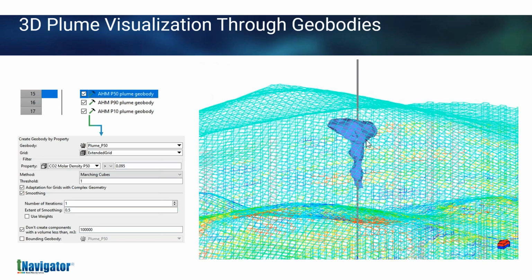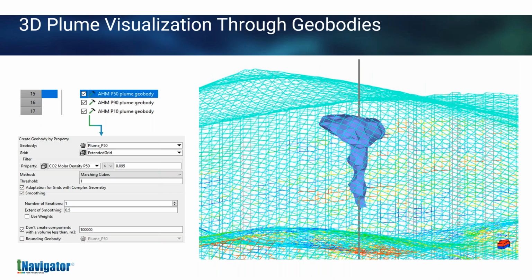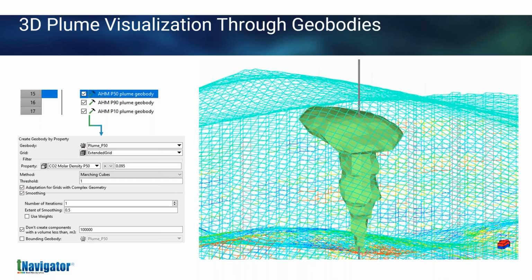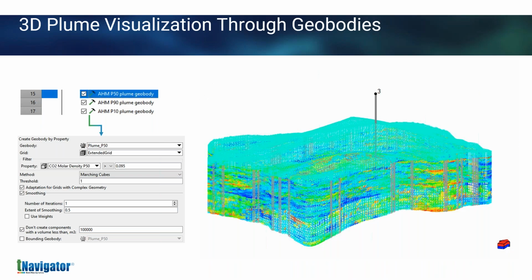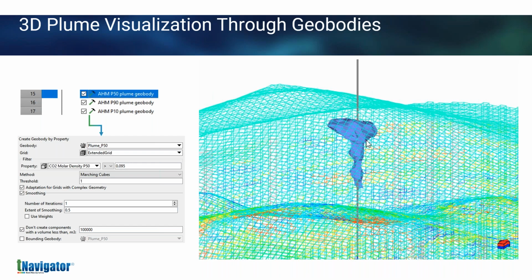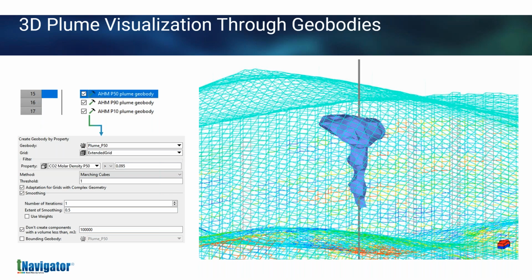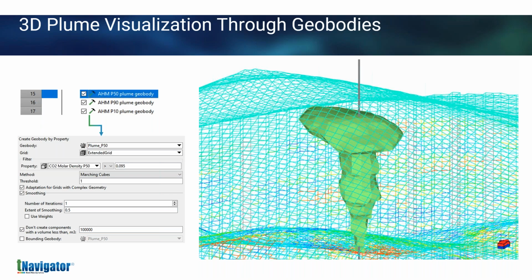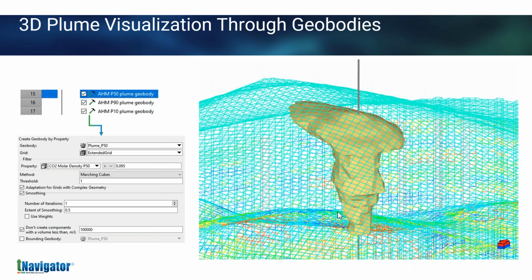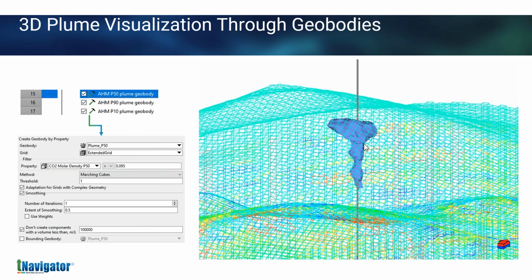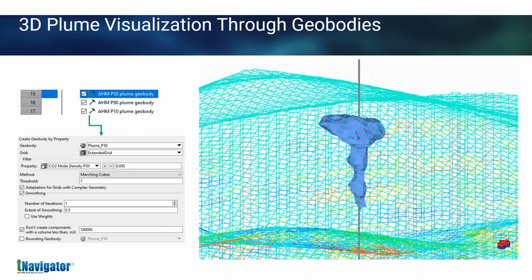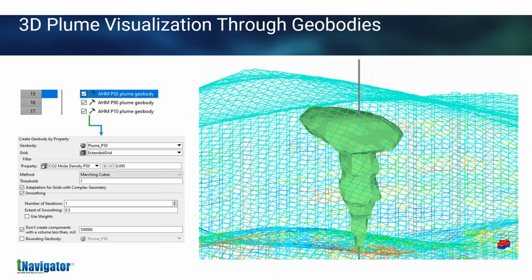We can also take the filters as we talked about, or different maps or 3D properties, and use them to our advantage to improve our visualization. In this case, what we've done is taken a property and taken a threshold for it, and everywhere this threshold is true, we have generated a property which then we use to fit a geobody around it. And you can see the geobody sizes moving from P90 to P10. And you can also do the same exercise through 10, just to make it more visually pleasing, if you like.